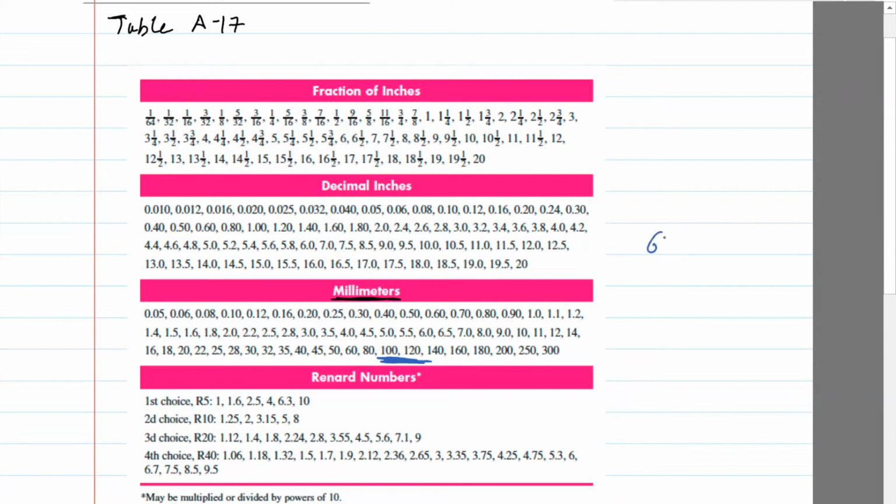we have stress is P divided by A, which is P divided by pi d squared divided by 4. So we can see that the stress is inversely proportional to the diameter. So the bigger the diameter, the less the stress. Given a choice between two diameters, you want to choose the bigger diameter, because if you go down to 100, and if you do the calculations, you'll see that your factor of safety will drop below 2. And you don't want the factor of safety to drop below 2. So we'll choose the bigger diameter.